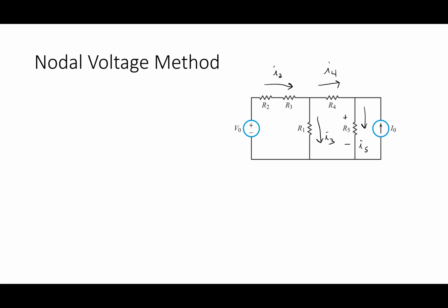In general, in any circuit, it has n independent nodes. So in this case, how many independent nodes are there? Does the ground count? Technically it does. So what we do is we call this guy ground down here, and we say that he is equal to 0 volts. That would be 3 nodes, counting ground.